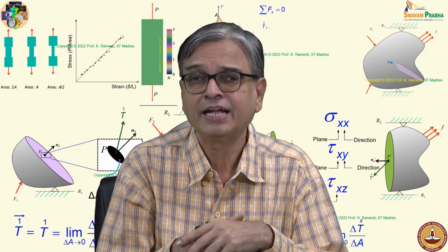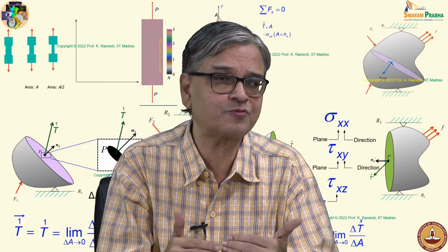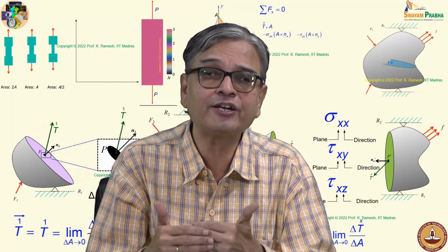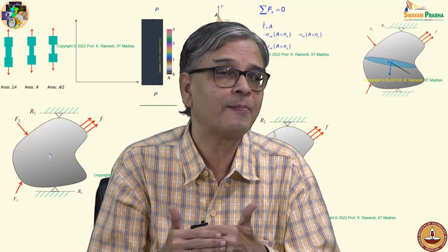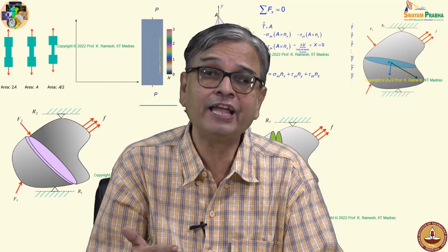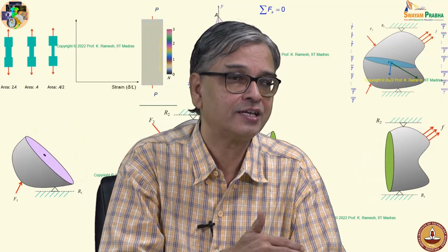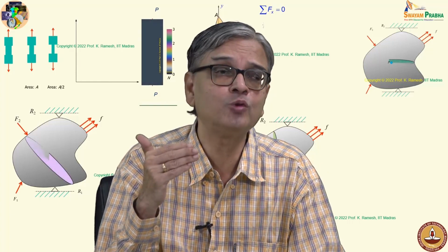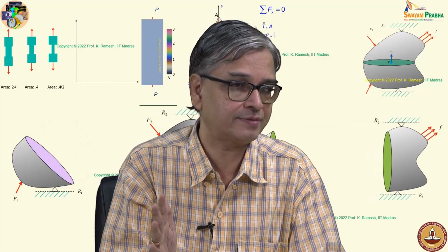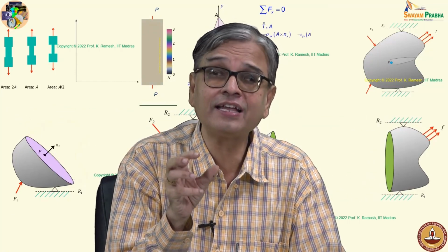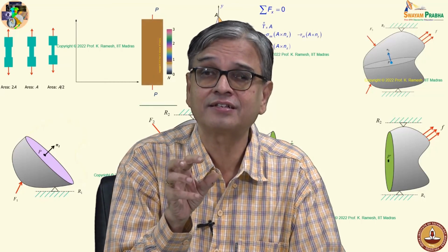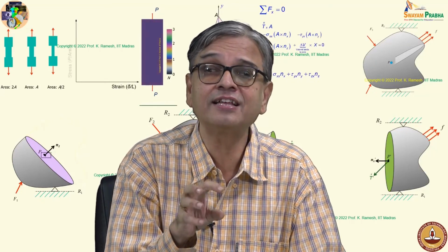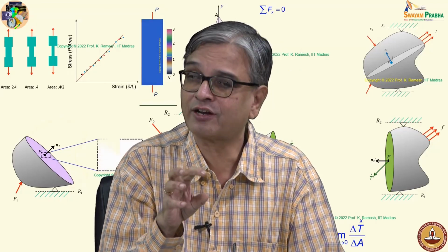Fine. And from the concept of stress vector, we graduated to how to find out the stress vector on any of the arbitrary planes if you know the stress vector on any 3 mutually perpendicular planes. That quantity resulted in a matrix. We said that is nothing but a tensor of rank 2.